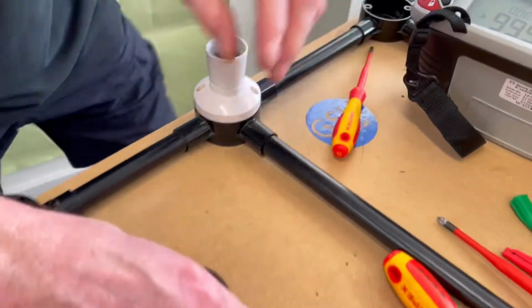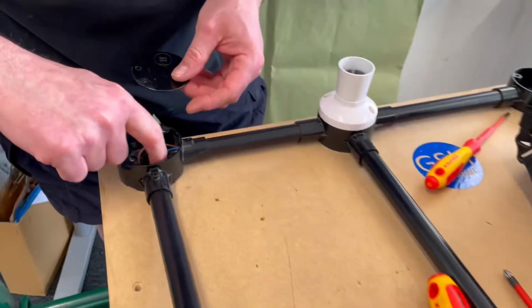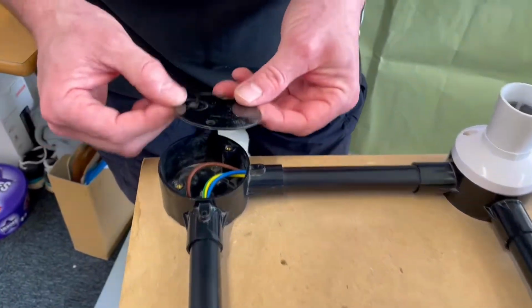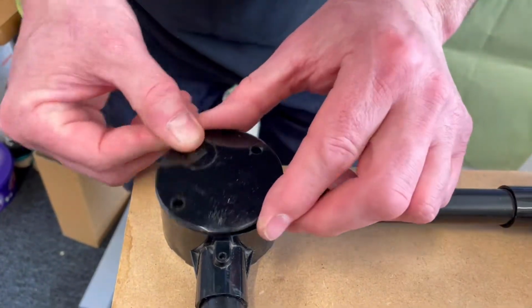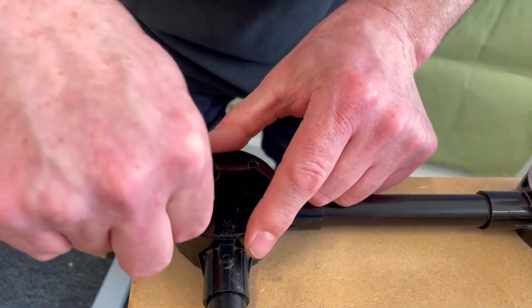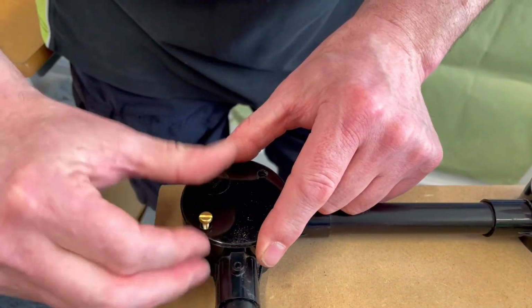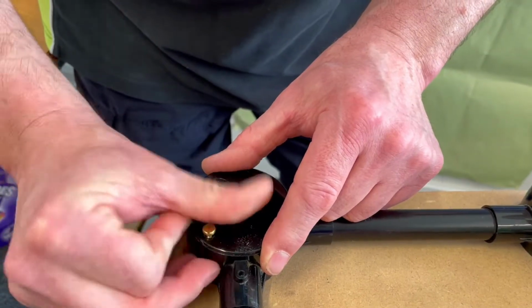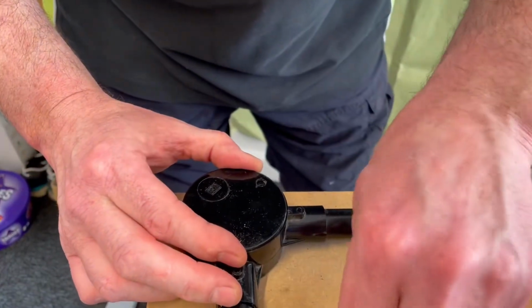I'm also going to put a lid on this corner because obviously we've got single insulated cables there, and if we're doing it properly we should make sure we put the box lid down. I know in a college setting often this gets missed because obviously we're not going to go live with it, but it is good practice to practice doing it correctly. So that box lid can go down as well.